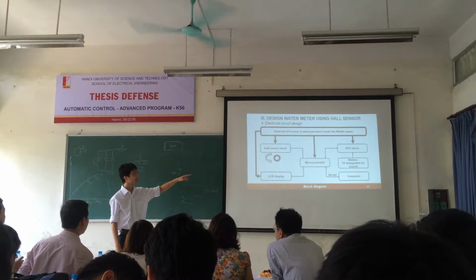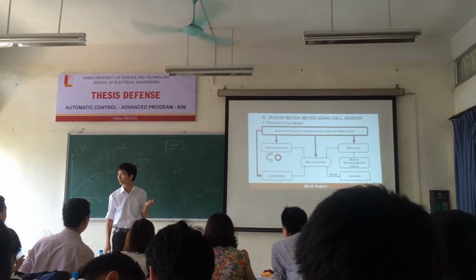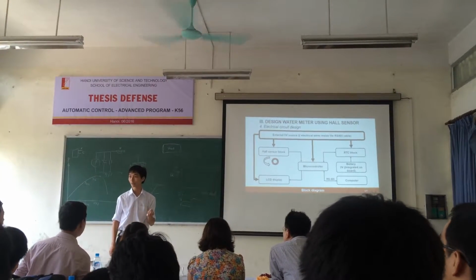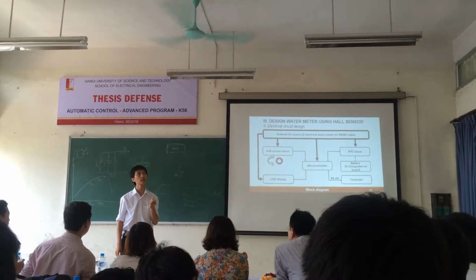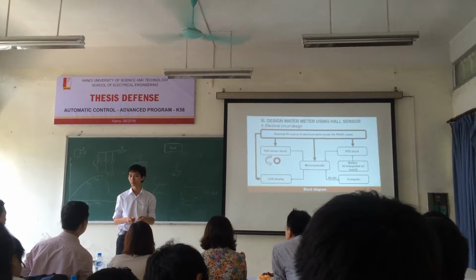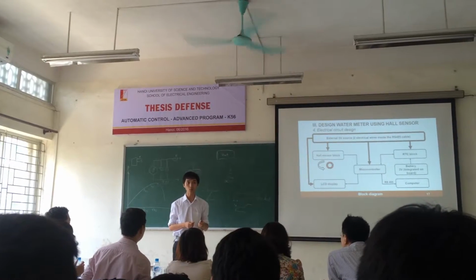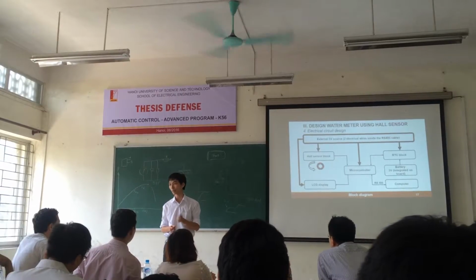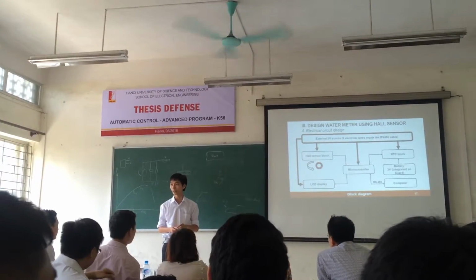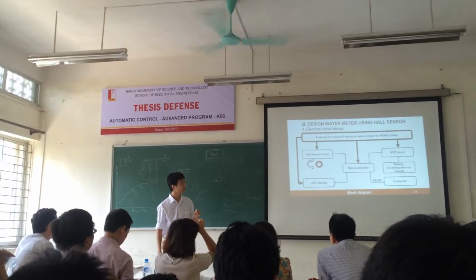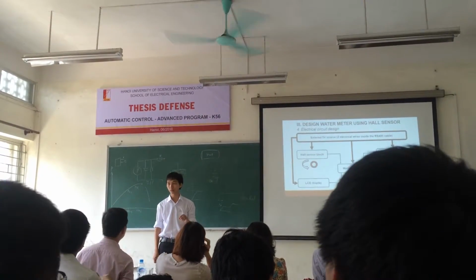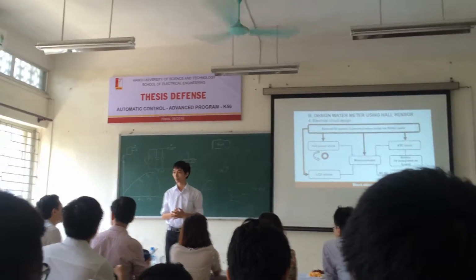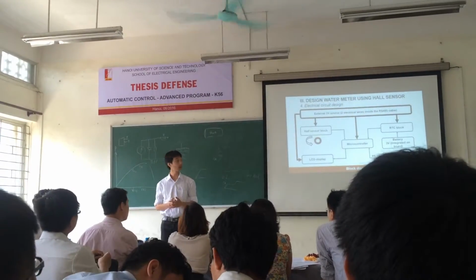When we replace the battery, it's not a problem, because the computer will automatically update the time for the meter. It depends on the reset, of 1 minute or 2 minutes. The computer will automatically update the time for the whole meter. So even if in one moment the RTC is not correct, after 1 minute or 2 minutes, data